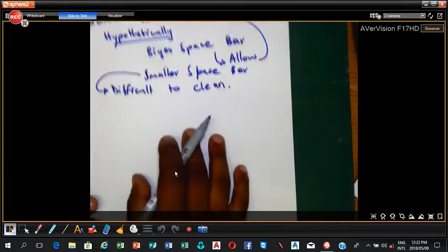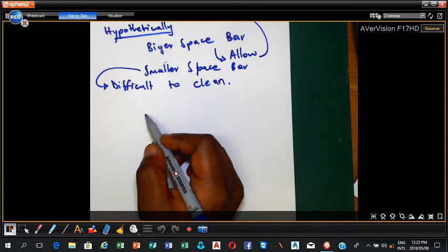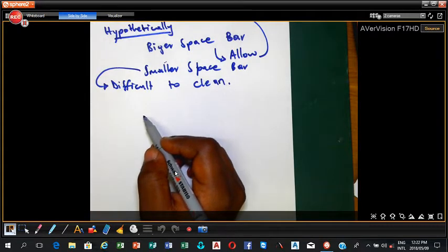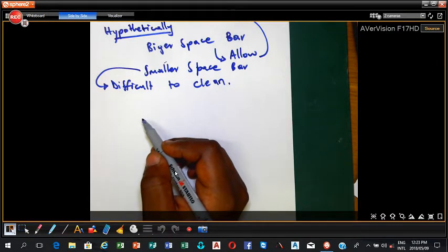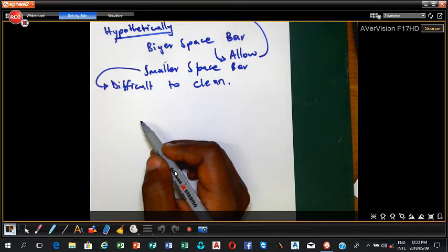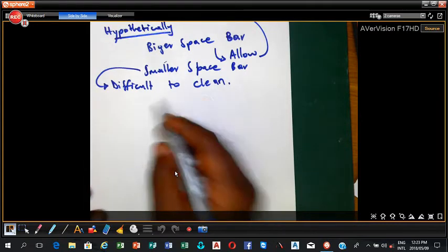Now, you are utilizing a mechanical rake through a conveyor belt, which is commonly used in modern plants, and you can only activate it due to the stoppage degree. We've already explained the stoppage degree, whereby you measure the sewage level from both ends, and then the difference determines such. And also the screens at manual operation are always at an angle with advantages on that, and at automatic the angle does not matter.